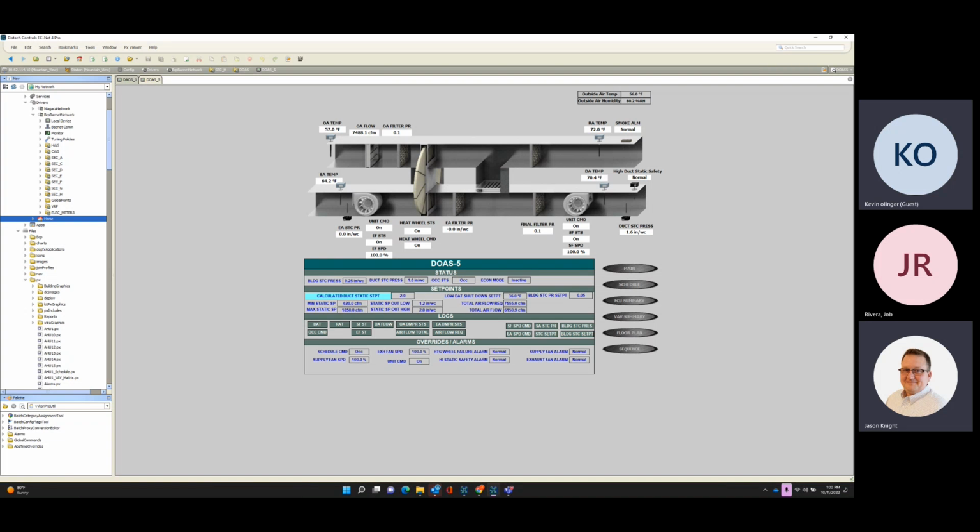So you went over high static. There are high static alarms on these, manual reset. We've got fan alarms, discrepancy between command and status. What other alarms are on these DOASs? Is there any kind of temperature alarms or anything else that we should keep an eye out for?